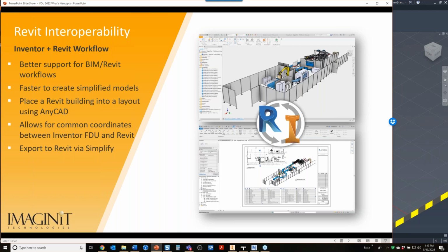And the Revit model maintains its coordinate system. So I can now export my layouts to Revit. You can now save your files as a Revit component. And if you built it in context of the Revit building with the proper coordinates, then the Revit user is going to be able to take your layout, put it into their Revit model, and have things populate right in place perfectly. So this has been a long time coming, and I really am glad to see how and why and where this information is located.